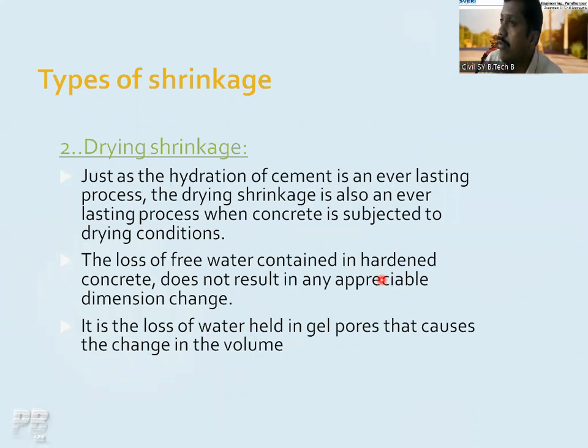If you are using a 20 mm size coarse aggregate, the percentage of air content is 1%. If you are using 10 mm, I think it is less than that. And if you are using 40 mm size coarse aggregate, the air content is around 2%. Okay? So in your concrete, definitely there are some gel pores.